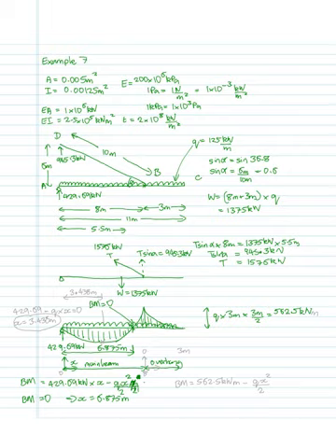And then that equation would continue. So we'll be looking later on from that equation to be running from 0 to 8 meters. And then if we had a look at the overhang later on, we might find, well, actually, if we wanted to find the maximum value down there, that's really the point where the shear force diagram is going to be equal to 0.